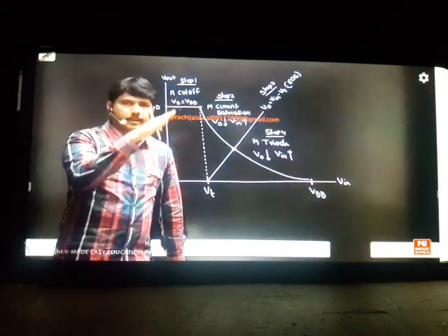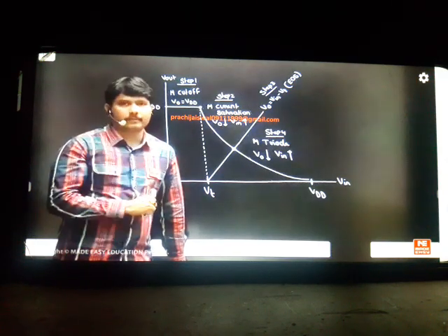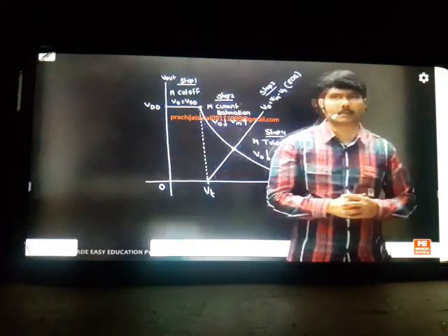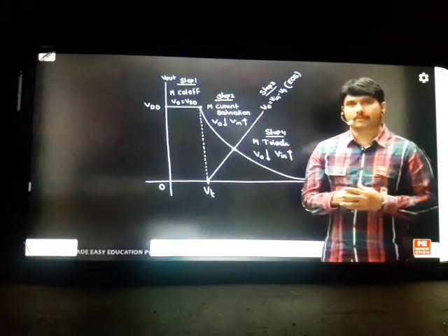When you are going like a parabola, you are spending time in the active region, which reduces the speed of your timing, called switching time. That's why it should fall vertically, linearly. But that is not happening in this case. That's why in digital design, whenever someone wants to design a good inverter, we never take a passive load. We are going for a new technique today called the active load technique.